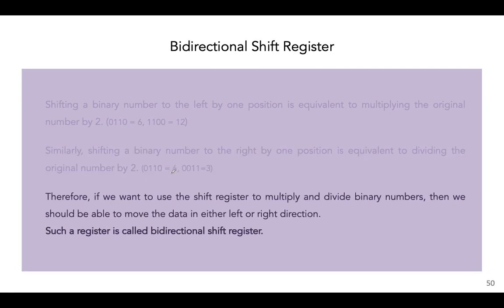So if we want to use the shift register for multiplication and division, because you already know that shift registers are used in calculators and computers to perform mathematical computations, right? So they're very handy when it comes to addition and subtraction. So if we wanted to use the same arrangement of shift registers to perform multiplication and division, instead of actually multiplying any number by the other number or dividing the numbers, we can just shift them by the necessary amount of bit positions, right?